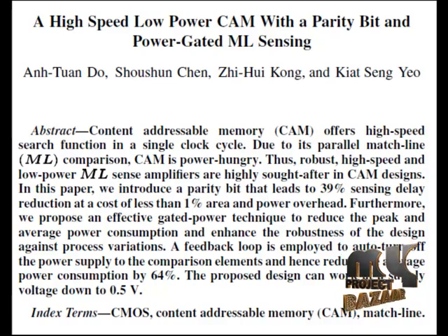To achieve effective data searching, the data comparison architecture of CAM is usually implemented in a parallel operation structure. However, due to this parallel processing characteristic, power consumption is always an important concern while designing the CAM circuitry. That is, content addressable memories simultaneously compare an input word to all the contents of the memory and return the addresses of matching locations in a single clock cycle.